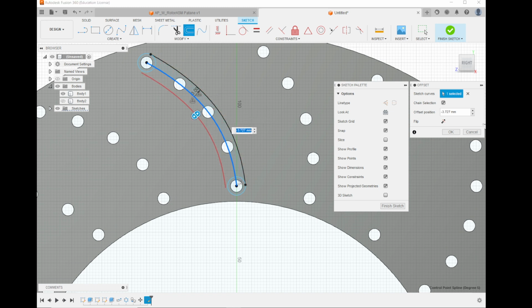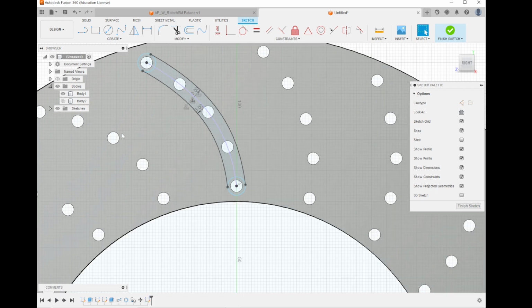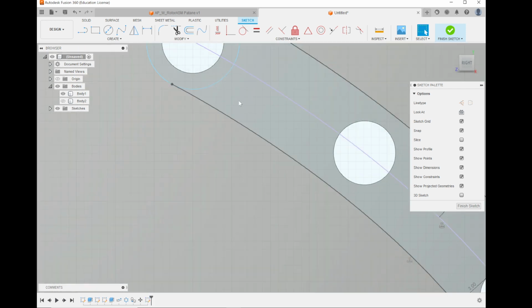And I know that my circles I made at the end are 6mm. So this is a time where you've got to make sure, if you're not using my numbers, your numbers match for this. If you're using 8mm diameter circles, this has to be 4. But I'm using 6, so I can change over here. This one's going to be -3. And if I press OK, we now see that the color's actually lighter blue now, so this is a sealed shape.